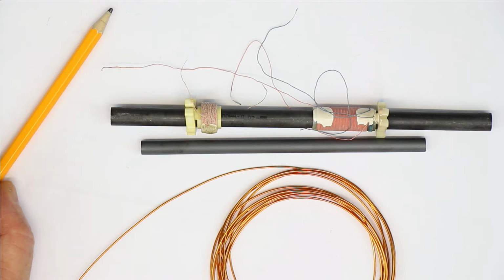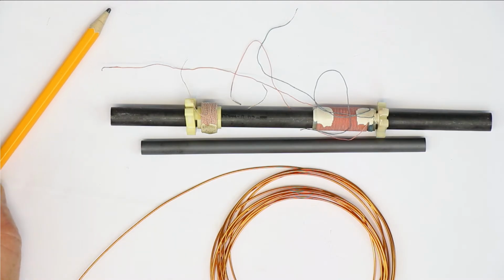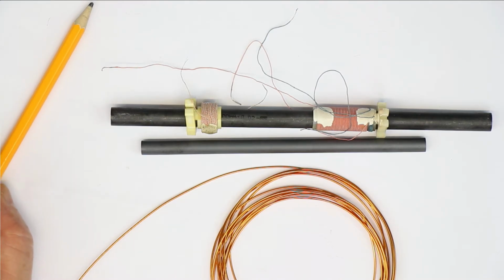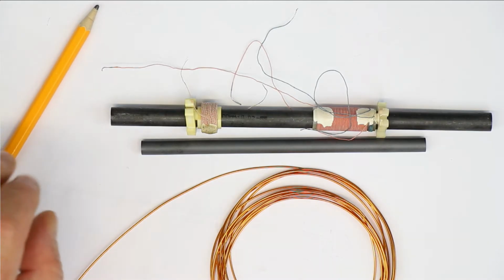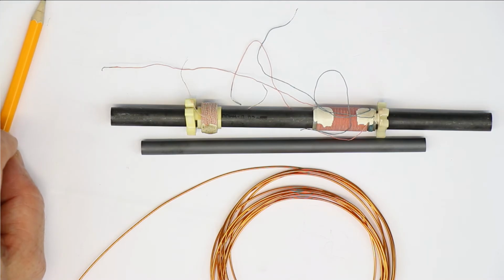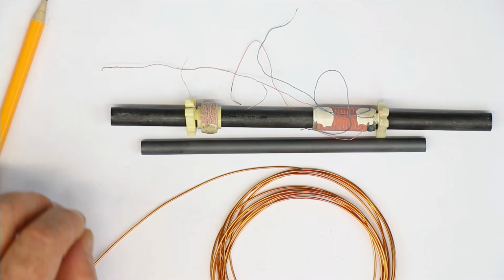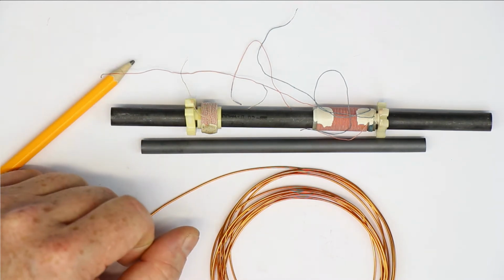And you know this from capacitors, that, for example, Teflon or PTFE or polypropylene are one of the best plastic film materials with the least losses. While other materials like, for example, PVC, which is often used as insulation for mains wire cables, is one of the worst materials. So which material should we choose?